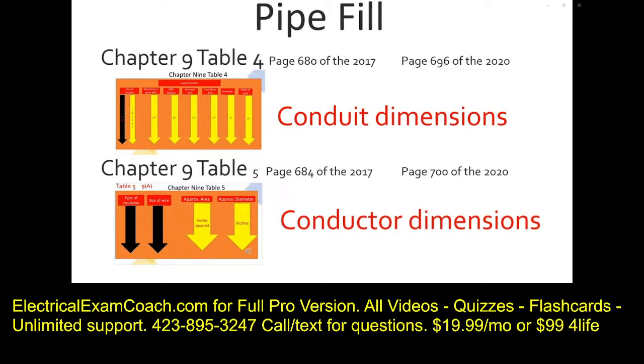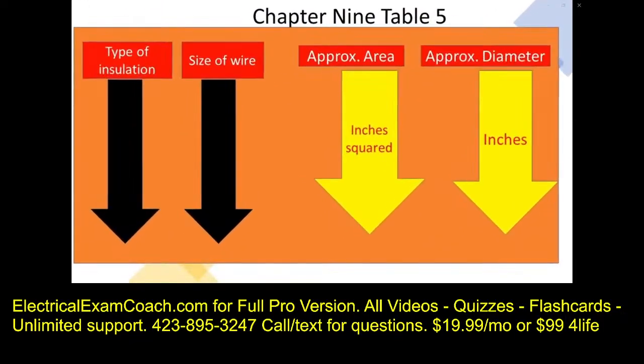Just like with box fill, each conductor has a size that it is. It is a square inch size when you're dealing with pipe fill. And we're going to head over and find out how to find that square inch value. Then we know all we have to do is divide, just like we did in box fill.